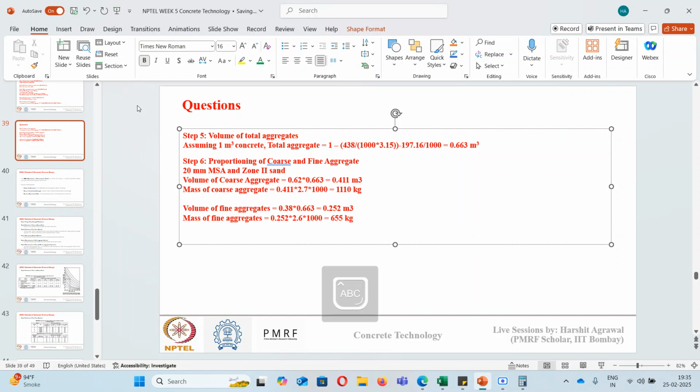Okay. Now step 7 is mixing coarse aggregates of different sizes. For this we need the sieve analysis results also, which we don't have right now. However, I will tell you, in general practice in India, we take around 50-50 proportions of 10 down and 20 down aggregates. But since we don't have the sieve analysis results, we will skip this part for now.